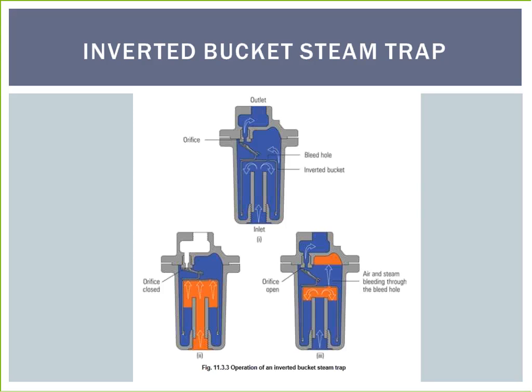At the same time, it must pass, and therefore waste, a certain amount of steam for the trap to operate once the air has cleared. A parallel air vent fitted outside the trap will reduce startup times.